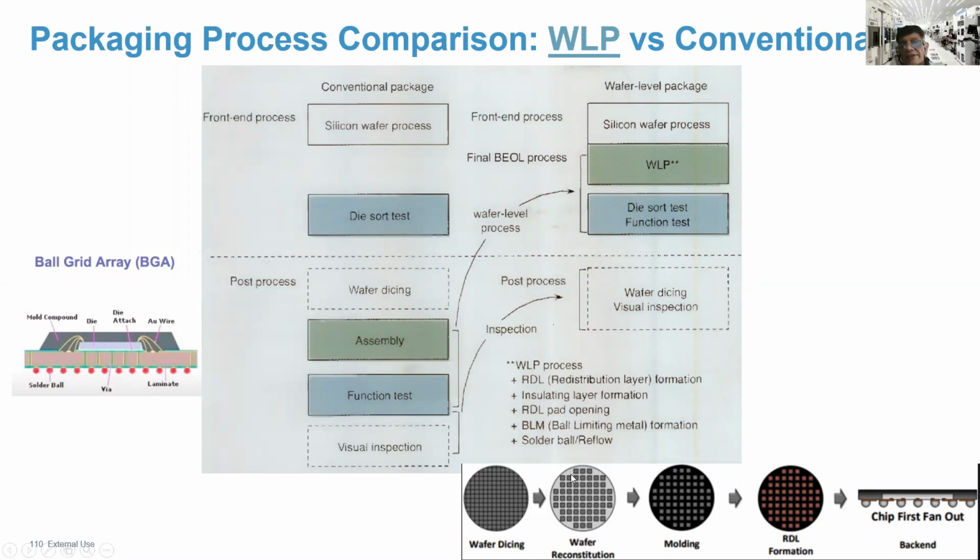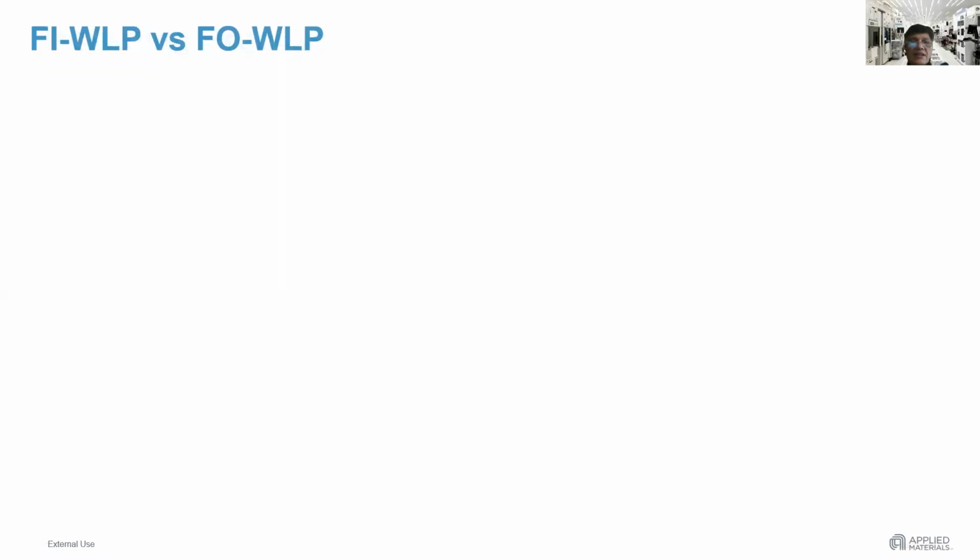On the carrier, you have an adhesive on which these dies are sticking, and on this you mold it, and after it is cured, you start processing it to create the redistribution layer with all the interconnects, and from there you are taking out the chip. So we'll take a look at this process a little more in depth, a slide down the line.